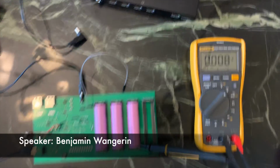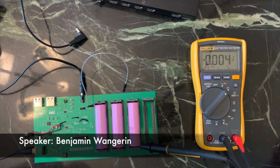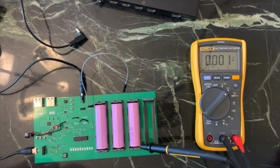This is the PCB for our project. What this is intended to do is supply 12 volts to our projector and 5 volts to our Jetson Nano MCU. What we have right now is the charging cable plugged in and the switch is not turned on, so all it should do right now is charge the batteries.